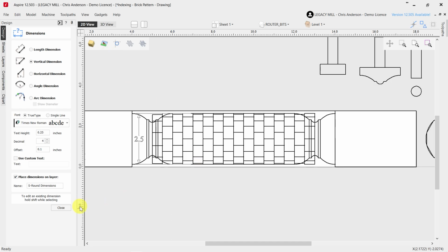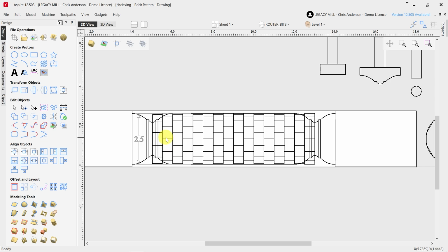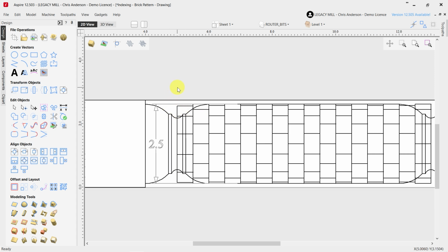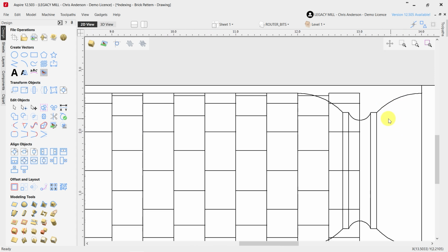Now the way this brick pattern layout is, you're always going to have the width of the cutter be back to back to back in the design, right? So I put the edge of this brick pattern on where the center of this tool profile cut is happening, okay, which was 5 inches from previous videos, and the ending position could be the same.